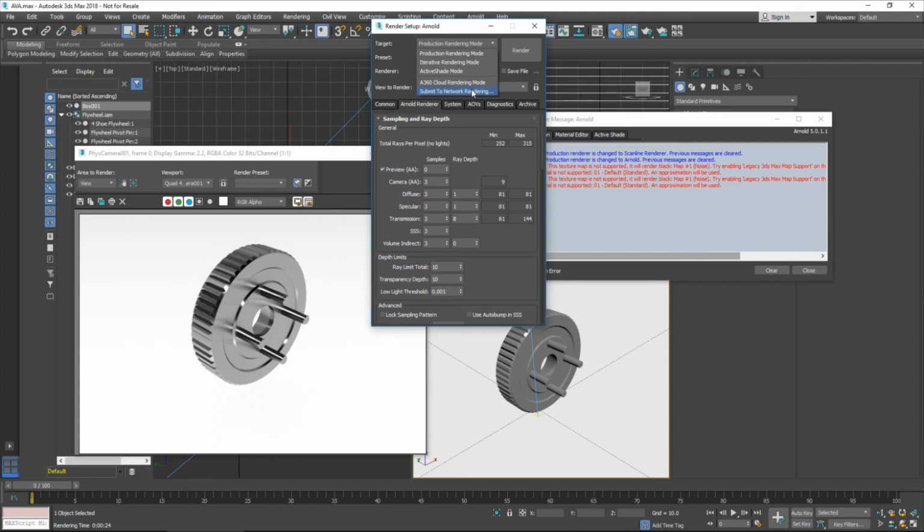So I think I saw a question about being able to render stuff like an IPN image exploding in like an Inventor assembly in an IPN, doing like an explode in that timeline. There are ways to do that. It does take a little bit more time in 3ds Max, but it's definitely possible. And then you can even render out each individual frame at whatever quality you want. And then you can stitch those together in a post processor, and you get an AVI or a video file basically. And it's definitely possible.